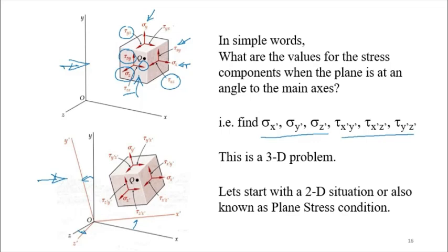So we have only three stresses remaining. And that will convert the problem into a 2D problem, which we call plane stress condition. Plane stress.